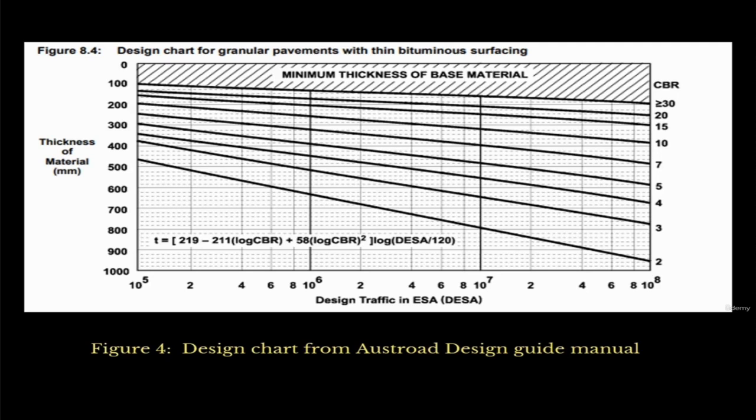The objective of that is to identify the different layers that you're going to have as you go down. Then you identify the slope change of the penetration curve. Every change in slope shows that you're now in a different layer. After identifying each slope change, you calculate the average penetration per blow for each slope change and calculate the thickness of each layer.